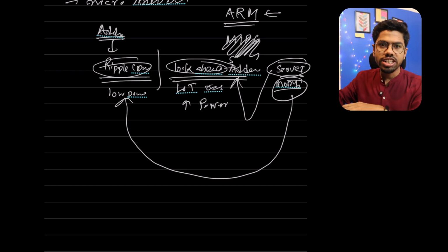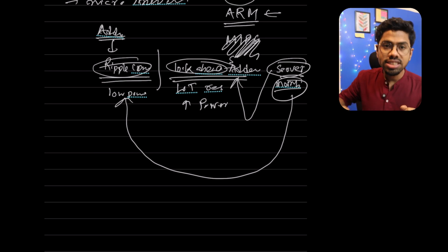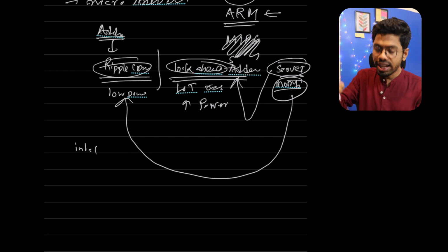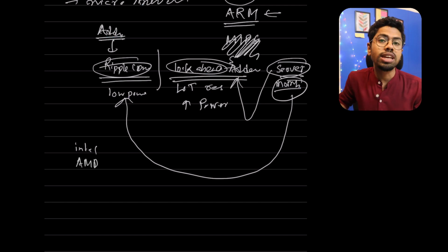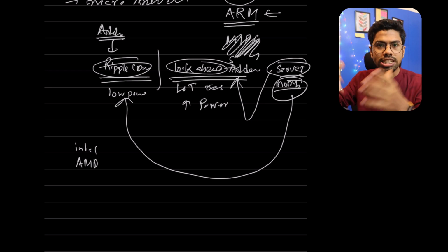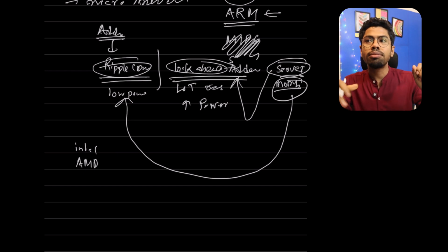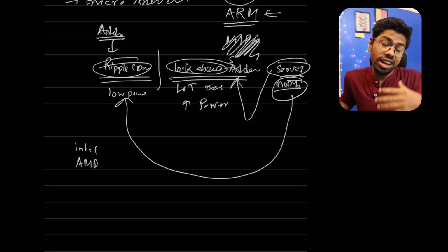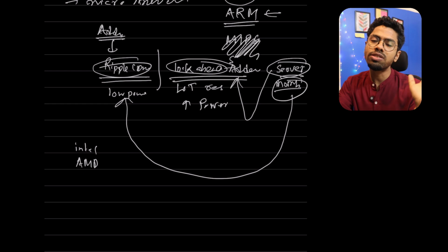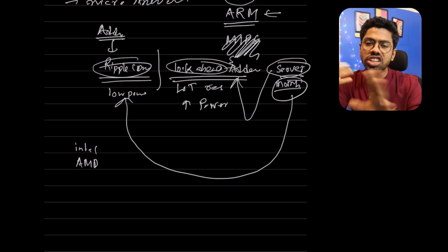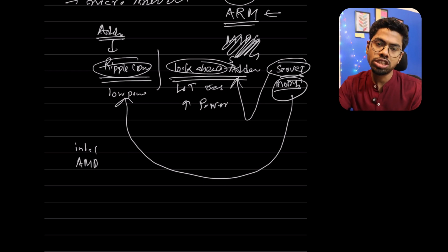Now what does microarchitecture mean? As I said, x86 is the architecture, right? Now your Intel based CPUs are also in x86 architecture and your AMD ones are also in x86 architecture, but you might see that sometimes one of the CPUs consumes less power, some is more efficient, some is producing more heat. Now if the architecture is the same, and I said architecture implies how many registers, or in a broad scenario, what strategy you are using to use your resources. Resources means memory locations, registers, ALU, IO pins, right?